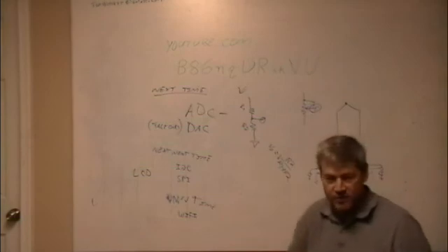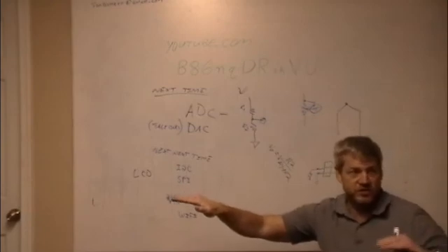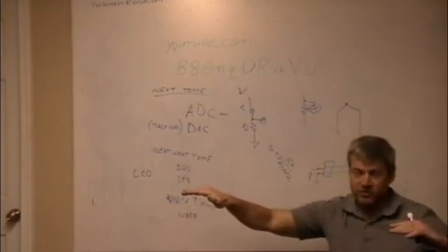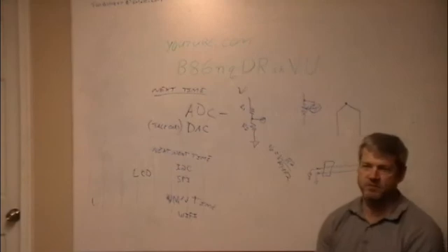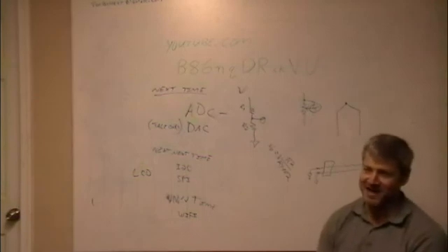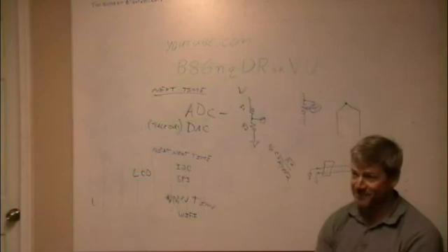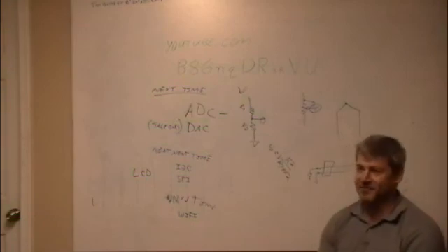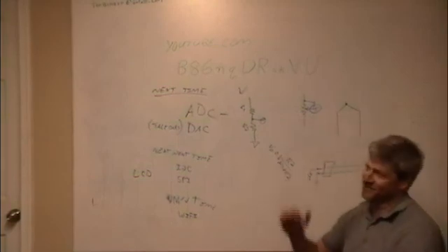What could happen is the room starts getting warm, and that means that the difference in temperature is going down if you're heating an oven, right? And so the control system thinks, oh, it's getting too hot in there, I'm going to dial it down. If you're smoking a ham, it's not going to matter. 10 degrees probably isn't going to make a whole lot of difference in how good your ham tastes. But if you're curing an epoxy that needs to be at plus or minus a half a degree for 3 days, or it's all broken, you're going to end up with broken epoxy. Your carbon fiber is not going to be laminated the way you wanted it laminated. So that's what the ice reference does.